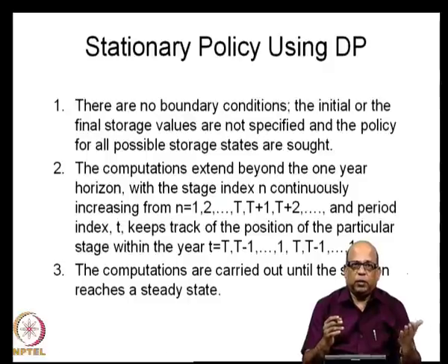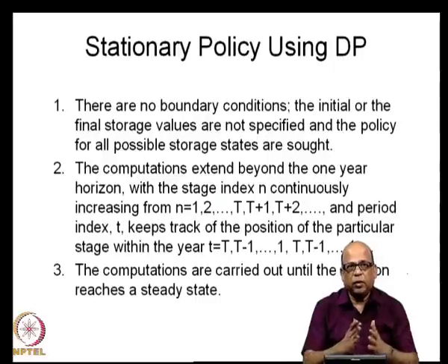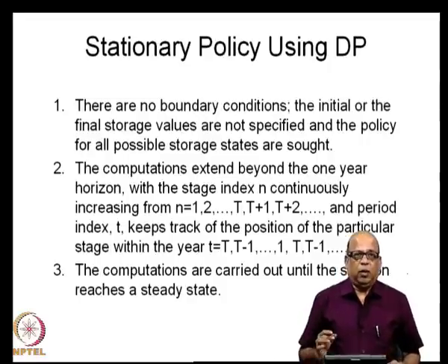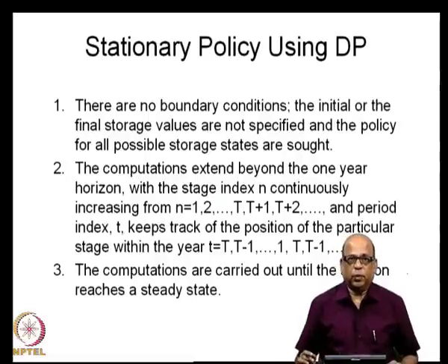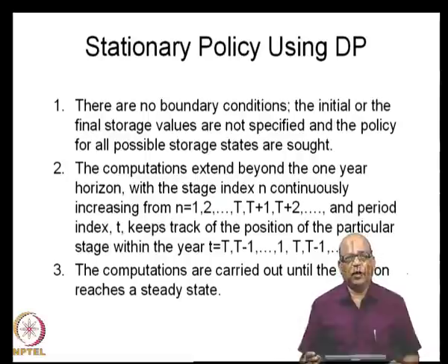You go to maybe lecture number 16 or lecture number 17, where I discuss the dynamic programming algorithm for arriving at the reservoir operating policy for a year. There we applied a boundary condition saying that my storage at the beginning of the first time period was a specified value. Let us say in that example we took S1 to be equal to 0. However, when we are deriving the steady state policy, you do not apply any such conditions either at the beginning or at the end.